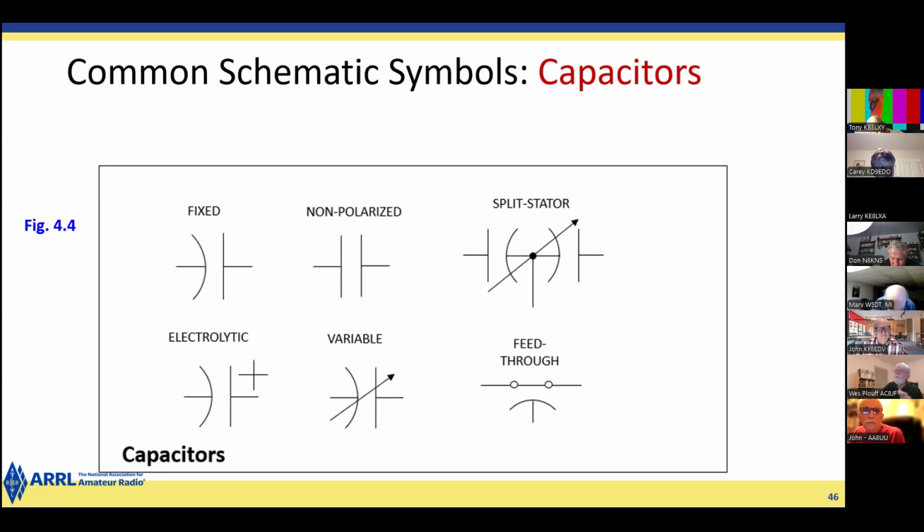And then there are variable capacitors, which are usually used for tuning. If you look in the inside of an old radio, that has a dial that turns when you turn the knob, you'll see a variable capacitor. There's a fixed section that has a whole bunch of plates that are half circle, and there's a moving part that fits in between.